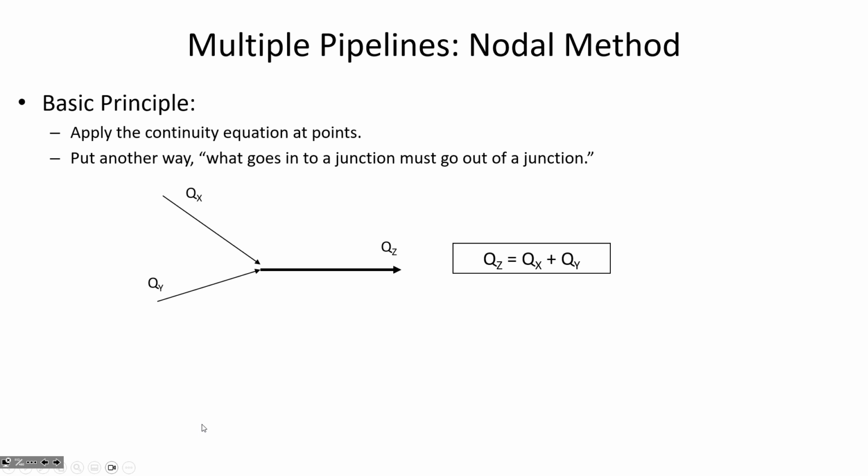And if it doesn't, then you knew that you needed to make an adjustment to either your guesses of the f values or, more probably, the amount of head at the junction. So checking the flow in and the flow out is an important tool that we'll apply on a lot of problems. The basic principle just says that if we have a junction where there's no potential for storage, the only option for an incompressible fluid like water is for the flow to go out of the junction.